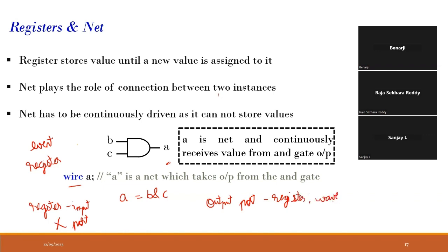The inputs might change, but we have defined how the output will change based on how the input changes. But for the input, we have no control, since it depends on external code and external modules. What values are passed to the input is not in our hands. That is why for an input to a particular module, you will have to use the wire data type.